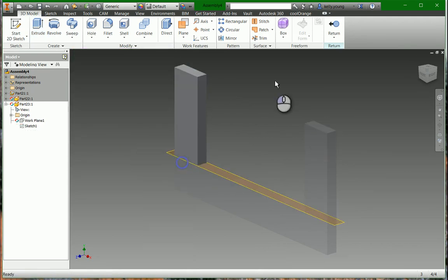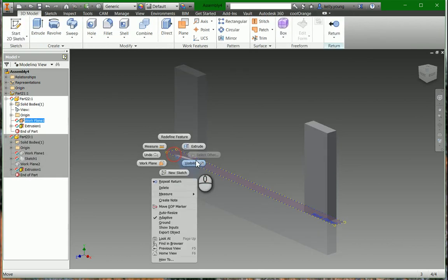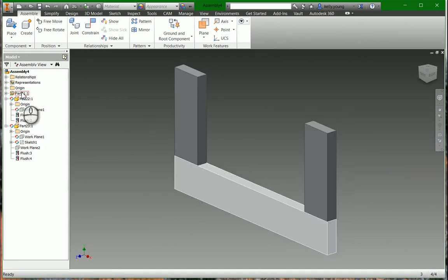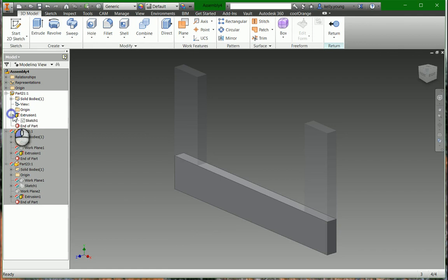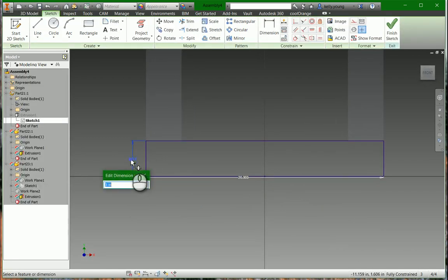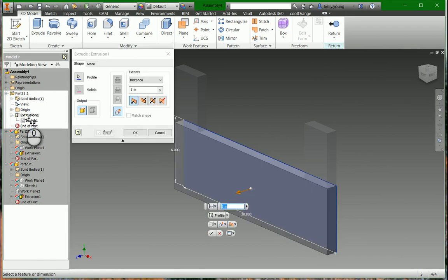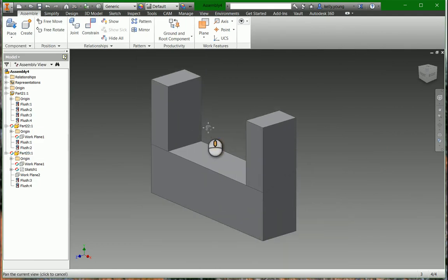So, the reason that we're doing that like so, then we can go back into here, turn this. So now you have your adaptive parts. That means that here's your original part that's just grounded at the root, then you have these other parts that are adaptive to it. So if we change this part into here to 6, you'll see that it updates. And let's make that big. So these haven't updated yet. If we come back to the main level, they'll update accordingly.